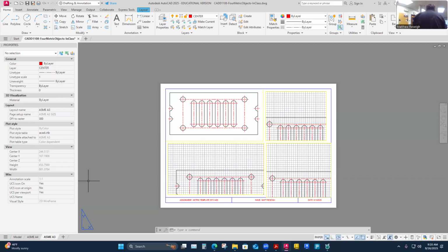I don't think the fillet likes that one on the other side, so I think that command would fail on you. Try it though. So to hit fillet, we need to hit distance or the radius, right? We need to always preload the radius because, if you remember with fillets and chamfers, the default is 0. So you won't see anything happen unless you set your radius and then choose.